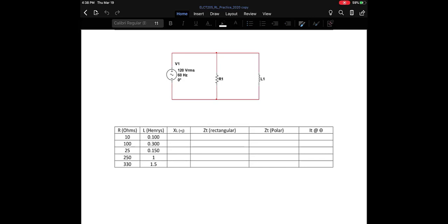That's really important. A lot of times students just want to jump right into an impedance triangle to solve for total impedance, and that cannot be done. If you did, you'd be telling me that two 10 ohm resistors connected in parallel equal 20 ohms of opposition, which we all know isn't right. So just remember that it has to be determined by dividing your current into your applied voltage to give you total impedance, or by using product over sum.